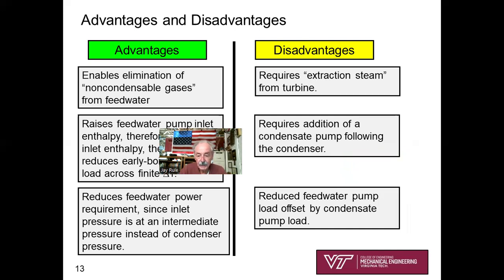It requires the addition of a condensate pump underneath the hot well of the condenser. And so basically, any reduced feed water pump load is offset by the condensate pump load. That's kind of a disadvantage.